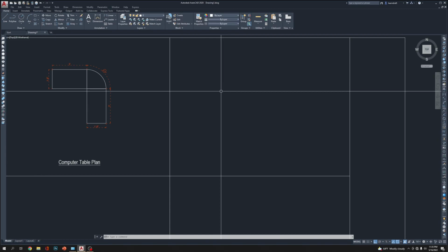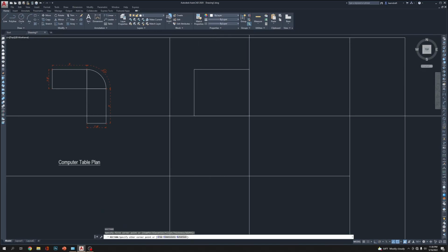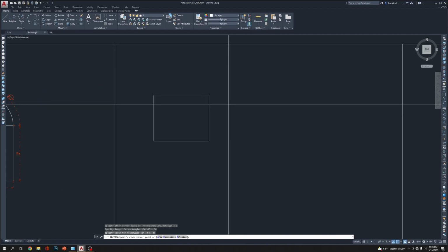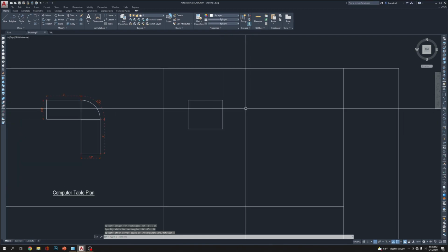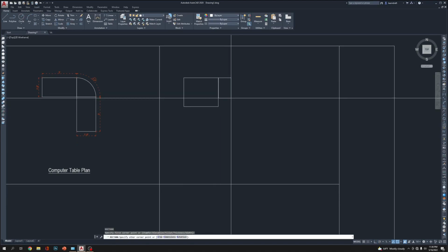Now we are going to draw the elevation. I have selected the 0 layer and let's do that. So I'm drawing a rectangle, D, enter. Dimension is going to be 36, enter, and height going to be 30. So this is how it's going to look like. Now click D, enter. It's going to be 20, enter, 30, enter, click.